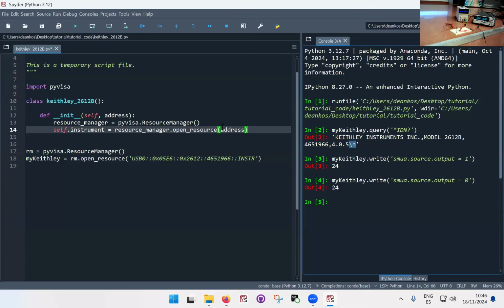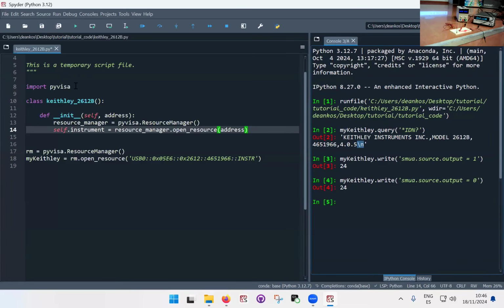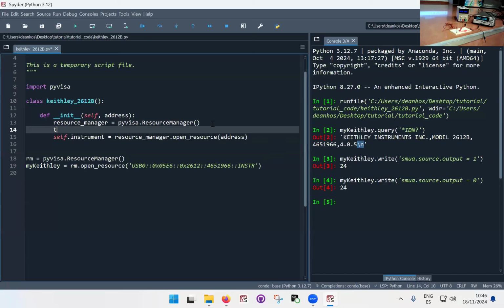So there's a little feature in the pyvisa library, so you can specify what the termination character is. So every time you talk to the instrument, the pyvisa will actually remove this character from the output, and this will save you some headaches in handling that little character at the end, which will always be present. So we can put this as the termination character, and in this case we know that for this particular instrument it's the new line character.